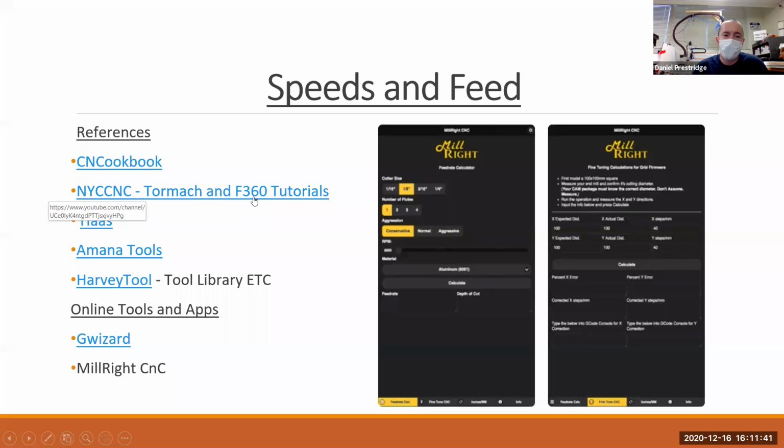And there's another thing called nesting, where you can take all of your parts and put them together in like the best little small package. And that's great for a bunch of different reasons, making sure that all of your material doesn't get wasted. If you spread it out, you have these pieces in between, that's a waste. But if you can bring them real close together, that's great.